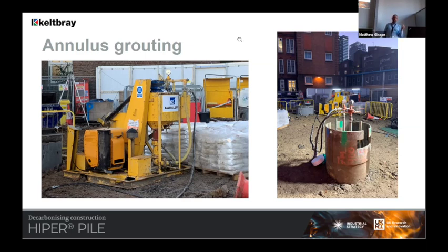because of the quality control about where they're manufactured. You know, they come from Brazil, they come from Spain, they come from India, they come from China. So there are many different constituents depending on the iron ores that go into producing the slag itself. So we learned the hard way that the EFC itself needs a particular grading of slag in order for it to work. And that's not what we'd normally expect.